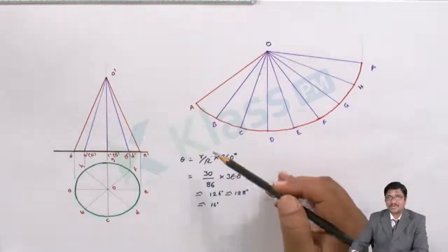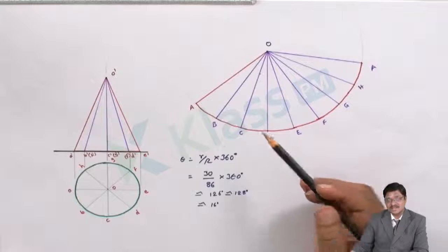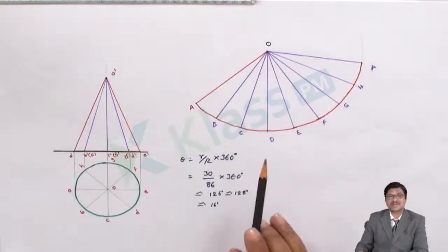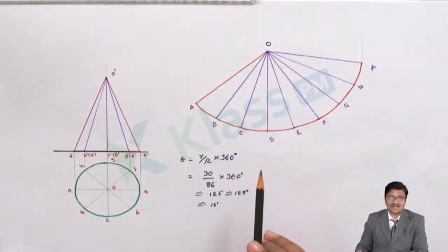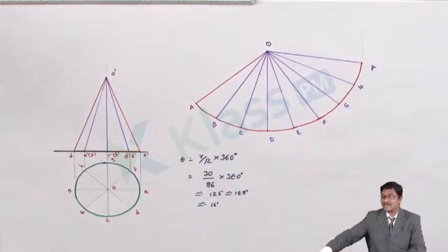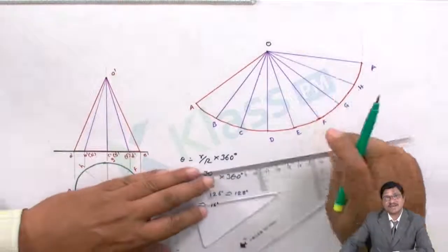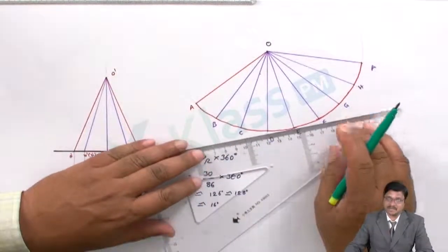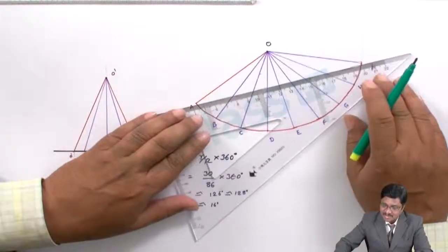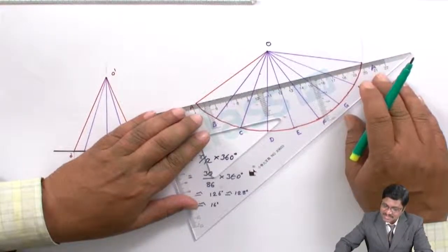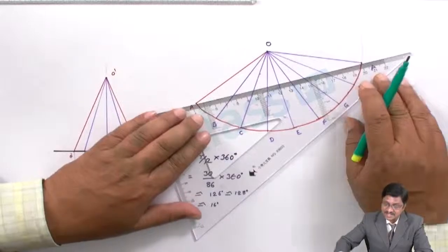Inside the curved part, we want to find the shortest distance from A to A. What is the shortest distance? It is nothing but a straight line. We can just connect by a straight line, measure the distance, and that will be the solution. The question does not ask anywhere to develop, but we are relying on the developed surface only for the solution. Now the development has been completed, so I want to calculate how much the shortest journey is.